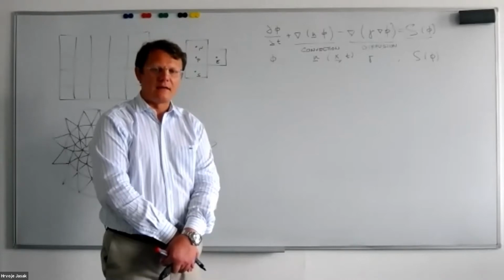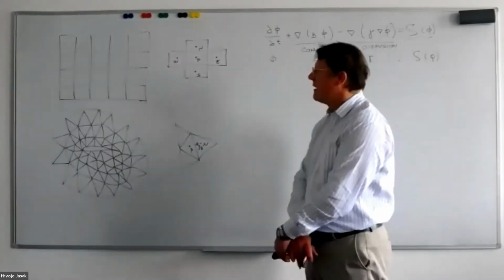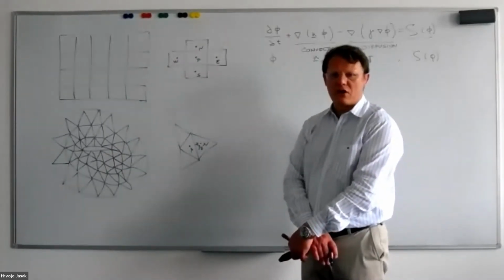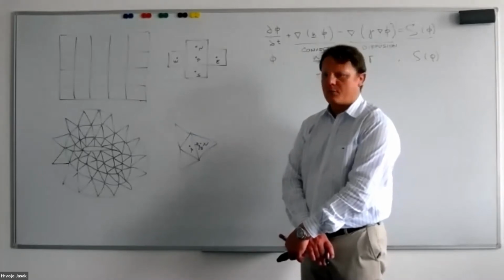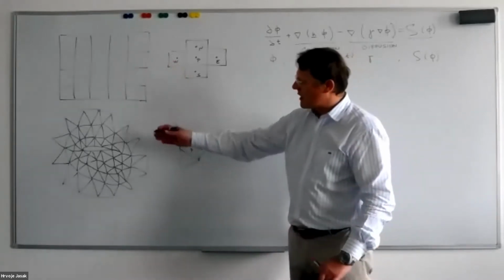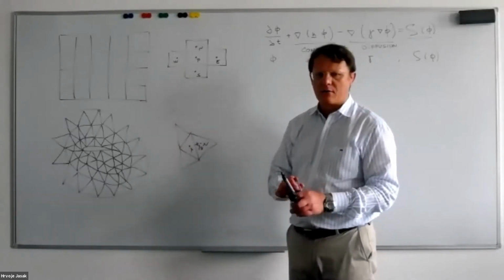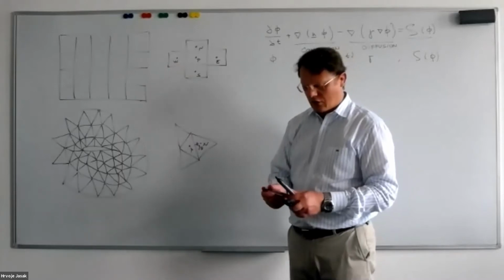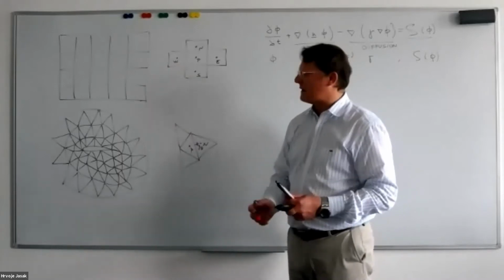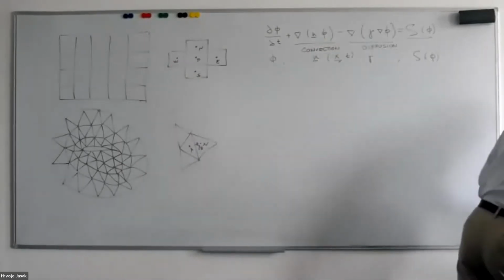The first step in the discretization is to describe the computational domain to my computer. And I will do that in the finite volume method using a computational mesh. Behind me, there are two types of computational meshes that I use on a regular basis. The first one is a Cartesian mesh, and the second one is a two-dimensional, unstructured triangular mesh. The bits that you need to notice here is that the mesh contains a set of control volumes. Let me mark one of them.